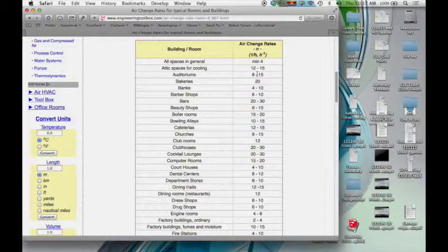This much air is going to move through the space, and sometimes it may have no heating or cooling, sometimes heat introduced, sometimes cool introduced. That's just an amount of air you have to move through a space. Even if you have a radiant floor system, or you're really counting on solar radiation, I still have to move the air. Sometimes I use the air to deliver heat or cool, but other times I just need to keep the air moving.